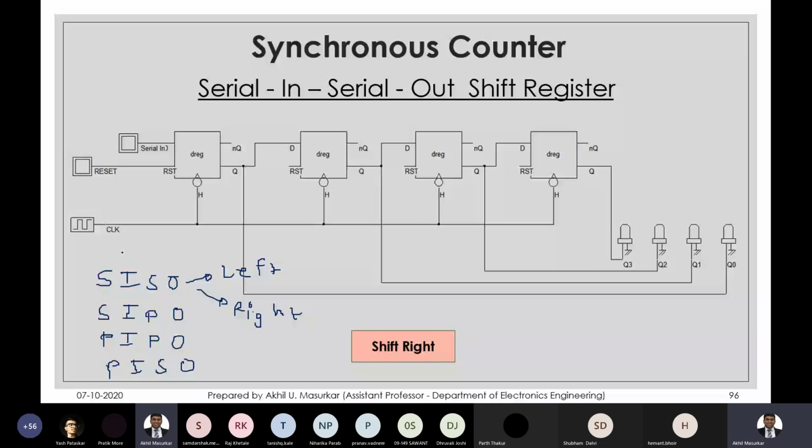The bits are coming serially inside. But your internal bridges for the microprocessor, let's say there is a 64-bit data bus, so it reads 64 bits at a time. So you will use 64 clocks to get your 64-bit data inside a register, and then you will read 64 bits in one go. That kind of operation is called serial in and parallel out.